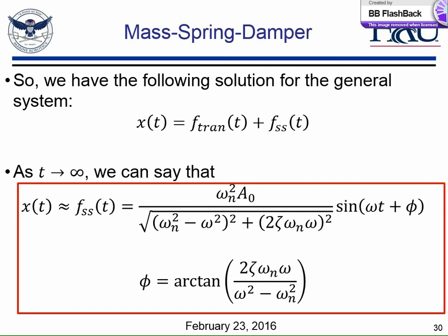You got that just because the omega is the only thing being multiplied by the t? Or how do you determine that if these aren't changing? What do you mean? Well, when we start characterizing a system, we have a mass spring damper system. Your omega n doesn't change because your spring constant and your mass don't change. So your omega n stays the same. And your damping ratio doesn't change because your damping coefficient stays the same. Your spring constant is the same, your mass is the same. So those are all constants. The only thing that's a variable is your driving frequency, omega.